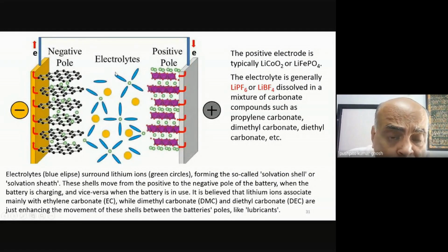Now, what you also must remember is that you have to try and reduce the internal resistance of the cell. Otherwise, there will be a voltage drop across your cell. So what you have to do is that, anything which can cause a problem, like for example, if I need to expand these lattices, then there's an energy requirement, so I'll lose some. If, for example, there are frictional forces between these molecules as they are sliding past each other, there would be a problem. There would be heat loss.